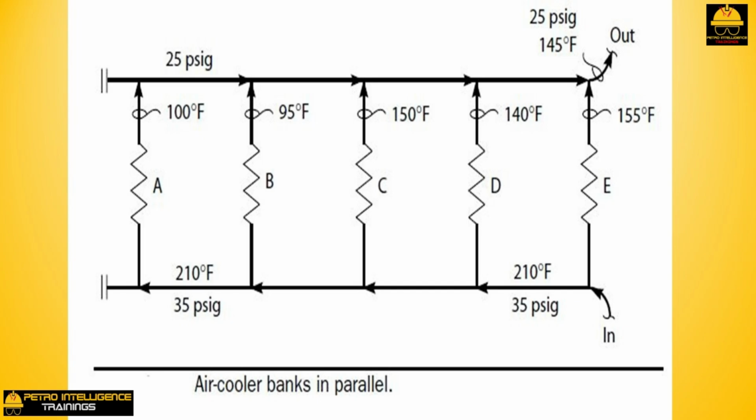7. The resulting wet chloride salts are very corrosive, especially to carbon steel tubes. 8. A ferric chloride corrosion product is formed. 9. This metallic chloride salt then reacts with the abundant molecules of hydrogen sulfide to produce hydrochloric acid and iron sulfide. 10. The hydrochloric acid may then continue to promote corrosion.